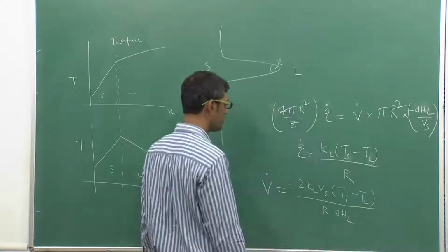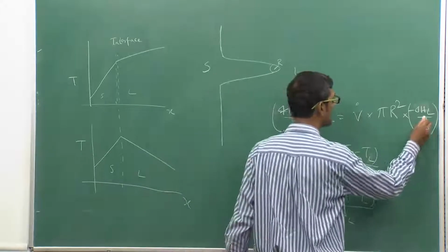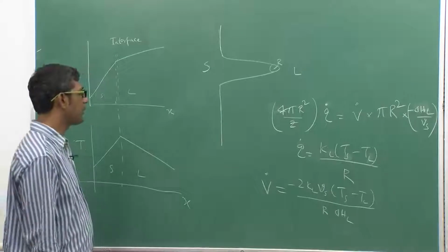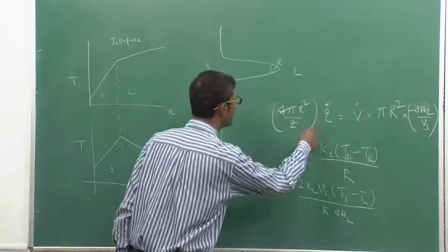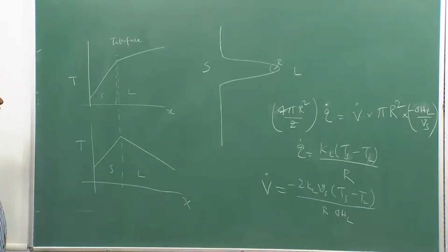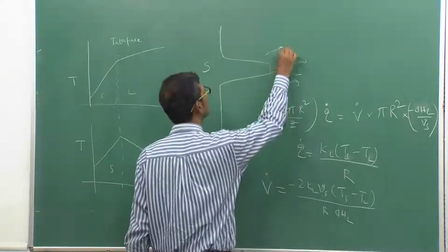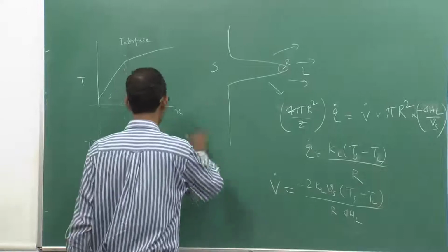correct. So, remember this V is the volume, okay, this V is not the growth rate, the V dot is the growth rate. So, finally, you can convert because we are basically using this term of Q and converting everything, that is why the R comes into picture. So, this is the maximum growth rate of a dendrite whose growth is basically dependent on the heat transport. Heat is critically transported to the liquid because liquid is undercooled, this situation is similar to this.